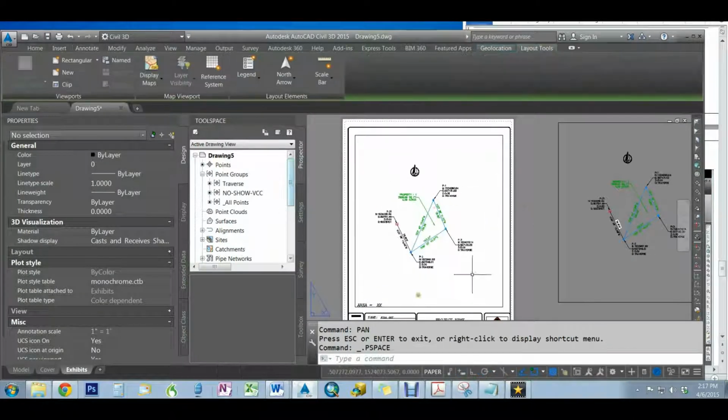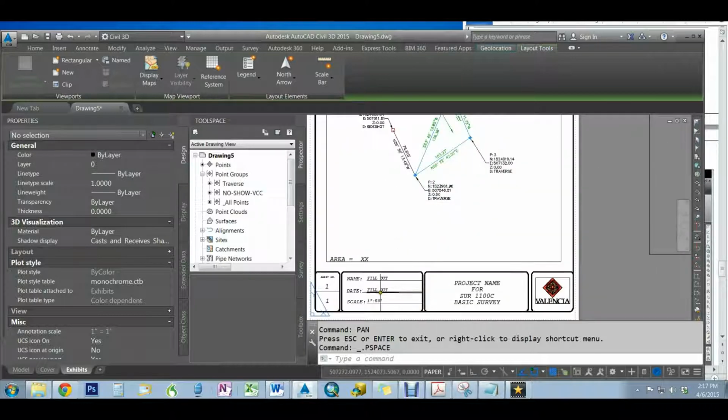Now, once you get it set up so that it shows your northings and eastings, your line work in your area, then you're ready to submit. Go ahead and change the text, update all your data. You'll have a 1 to 50 scale. If you decide to do a 1 to 40 or a 1 to 30, make sure you change your scale.